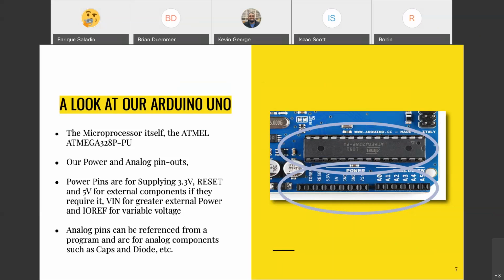On the bottom, you get one set of pins. On the left hand side, you get the power in and out. So you're able to simply run 5 volts, 3.3 volts off the board itself in case you're not able to get standard 5 volts or 3.3 volts from an external source. You also get the grounds and the inputs in case you do want to run internal power, but you don't have a barrel connector. And then the bottom right side, you get the analog input and output. So you get digital input output and you get analog input output.